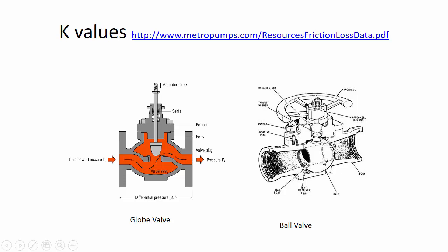You remember down in the hydraulics lab, the pipe rack, those yellow handles that you can just immediately take from horizontal to vertical, and then the pipe stops. Those were ball valves, where all it takes is, I guess it would be a quarter turn, and the flow is shut off completely.